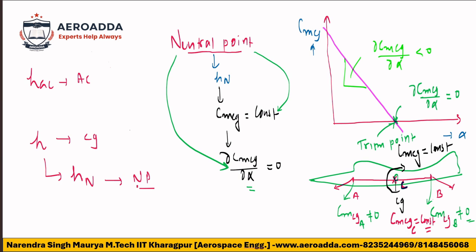It's very easy. Aerodynamic center, you will always talk about for the wing of the aircraft. You will find the aerodynamic center along the length of the chord, which is for the wing only. But if you talk at the broad level, that is the airplane or aircraft, then it will be just like a neutral point. So the neutral point is always one parameter defined for the complete aircraft.